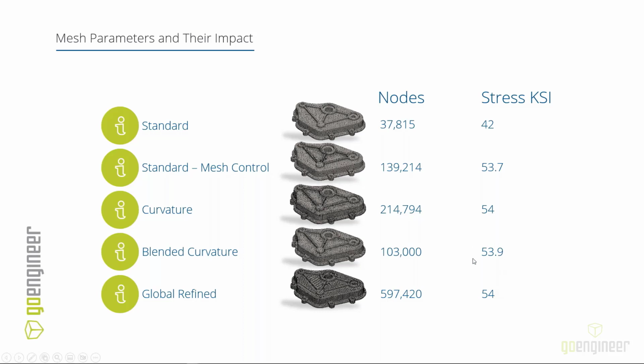That's because this was a pretty well converged mesh. This was a pretty well converged mesh. And this was a very well converged mesh. So my recommendation, personally, I stick with a standard mesh with mesh control. Curvature would be my next selection there.